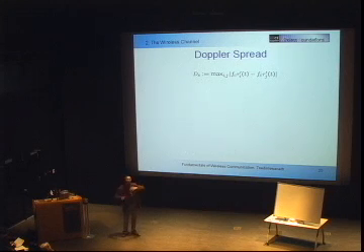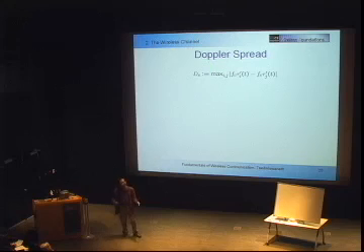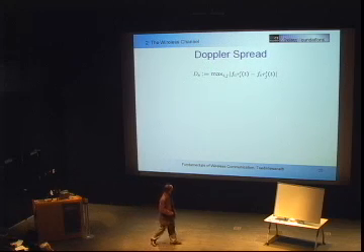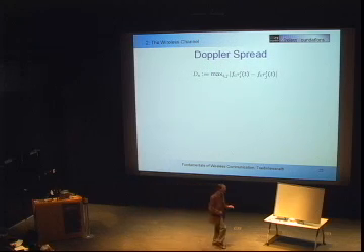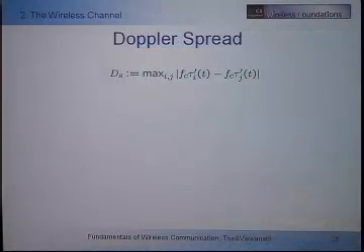You can have a very large delay spread and a very small Doppler spread, and vice versa. It's not necessarily correlated. So that's the first thing: to make sure that all these quantities are defined in terms of the delays of the paths, but they are very different quantities. One is the delays themselves, and the other one is the derivative. Okay, that's number one.